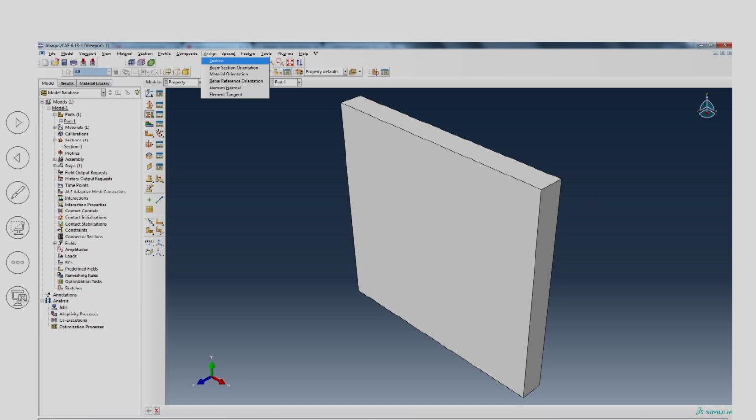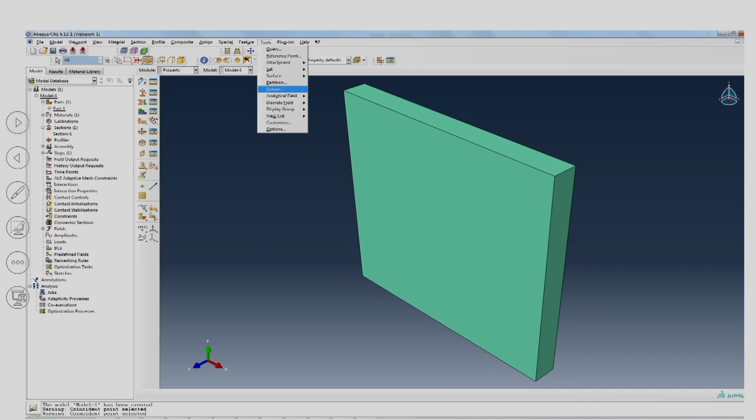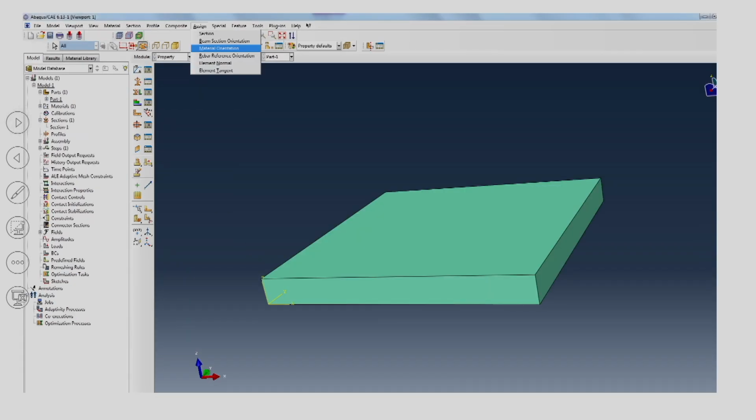You put in the Young's modulus, then you have to decide the homogeneous section, then apply that sectioning, then create the datum reference. When you talk about a generally orthotropic material, then you have to provide an orientation, but for the case of isotropic you need not.